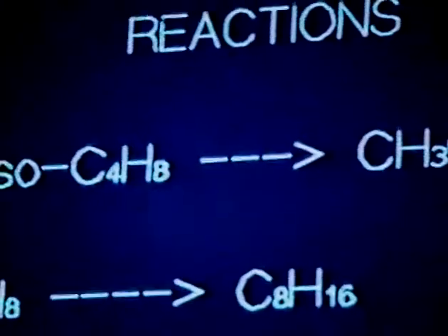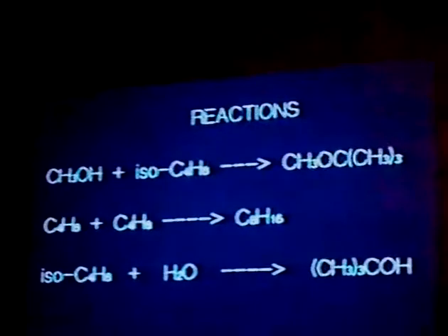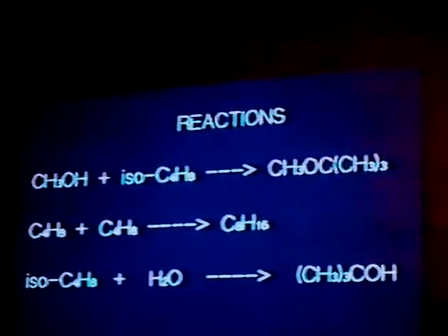The major reaction shown here at the top of the slide is that methanol reacts with isobutylene to form the MTBE. Methanol is generally in excess, and the isobutylene, the limiting reactant, is normally in a mixture of several C4s in the range of 30 to 40% concentration. These C4s typically come from a cat cracker. The other C4s in the mixture tend to be inert at reaction conditions.